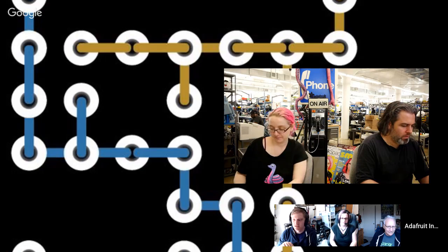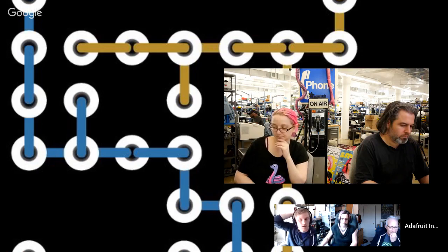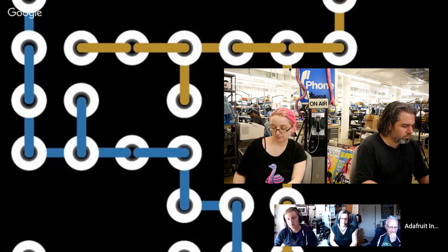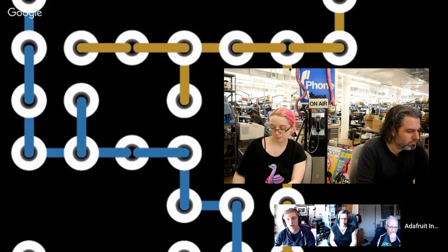It's a good question. And I hinted at it earlier, and I should type this out too. When I was first looking at MicroPython and the machine API, it felt very oriented towards the actual structure of the MCU and abstracting the commonalities of MCU structure. Whereas as I looked more and more into that, I went into the world of, here are the different sorts of behaviors I need, and then just writing modules based on behavior rather than structure. And so that's what my advice would be: design your API for what you want to achieve, not for the tools that you have at hand. Which I will try to write into here. Yeah. If I can find it.